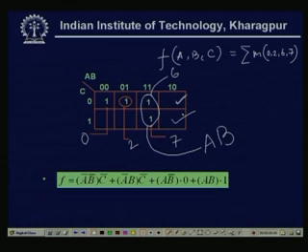That means, what I am doing, I want to design these combinational circuits using a multiplexer. So, for this multiplexer, earlier what we have seen is that all 3 variables I made the control inputs or the select lines. Now, I want that only 2 variables are the control inputs.